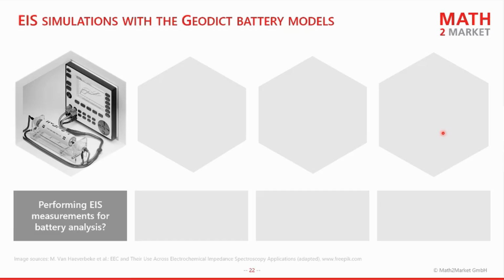We have learned now how you create the battery electrode microstructure and how we predict the charging behavior of the electrode cell in a fully resolved or homogenized P2D Newman model to parameterize your materials for the model. Often electrochemical impedance spectroscopy, EIS, is used as a non-destructive characterization method for battery cells.